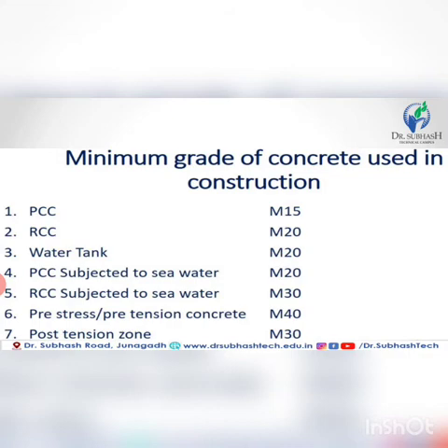Minimum grade of concrete used in construction: for PCC, plain cement concrete, M15. Second, RCC, reinforced cement concrete, M20. Water tank M20. PCC subjected to sea water M20, RCC subjected to sea water M30, pre-stressed pre-tension concrete M40, post-tension zone M30. Minimum grade of concrete used in construction.